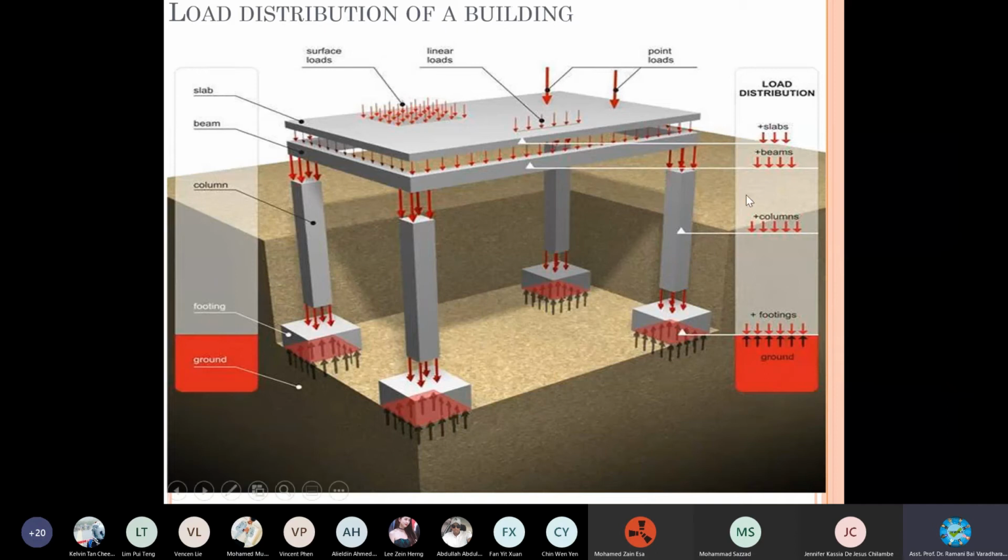All of you know that these structures bearing the load have to be designed properly to support the building for all types of load. Just now you studied 3 types of load: dead load, imposed load, and wind load. Wind load is mandatory if the building is above 3 floors. Up to 3 floors, like a residential building or bungalow type constructed in your compound, it is not necessary that much. Generally speaking, up to 3 floors you can still design without wind load. It's applicable above 3 floors. Like how much is the height of each floor? Any idea? A rough idea about the height of each floor?